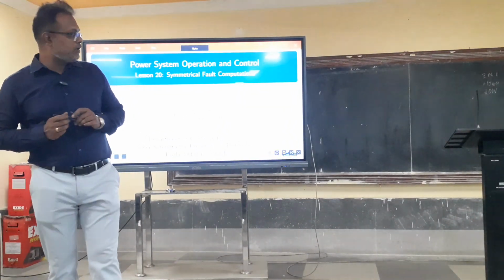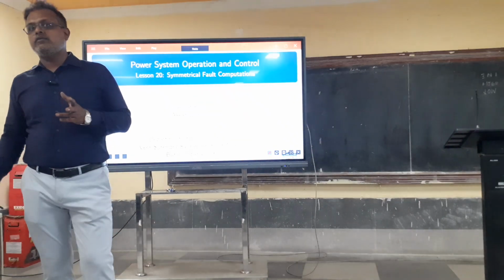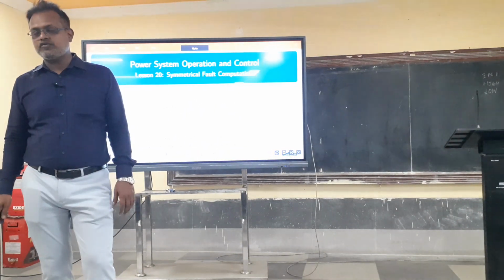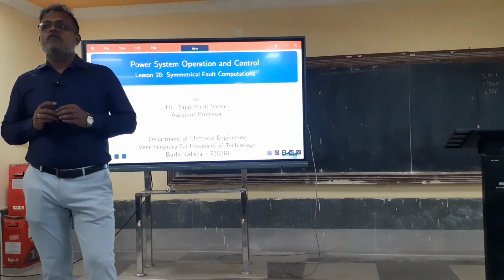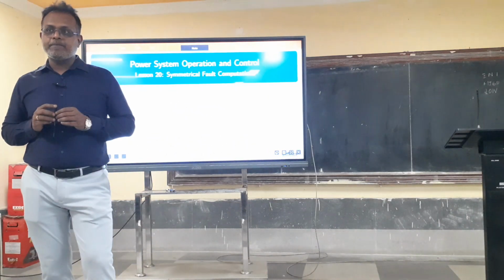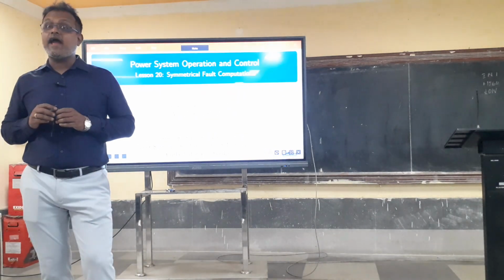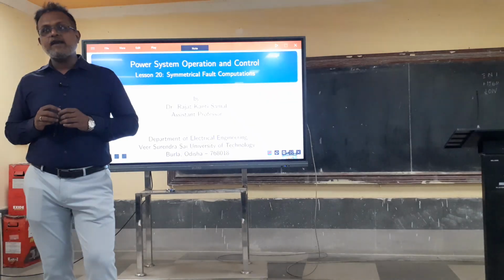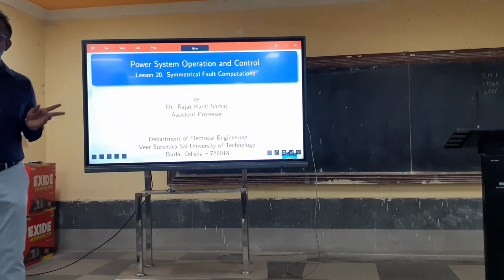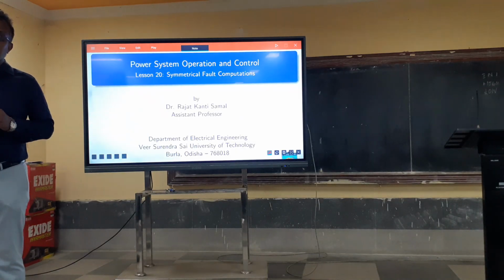Okay. So in the next two classes we will discuss how symmetrical fault is computed, which is mostly important for sizing of the power rating of the circuit breakers. How much current a circuit breaker at most will handle, that we can know only from symmetrical fault computation. Today we will discuss the Thevenin theorem method of computation manually.